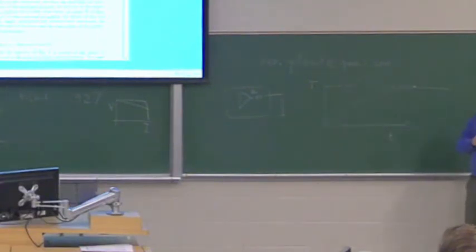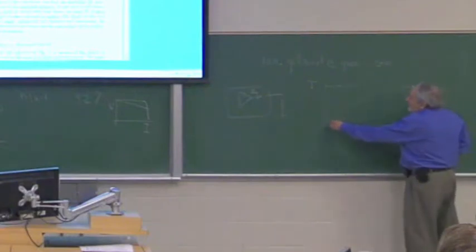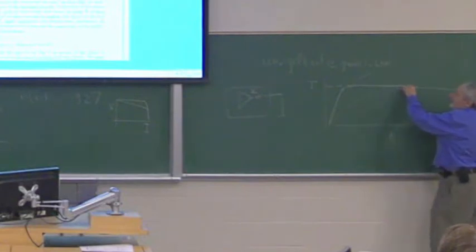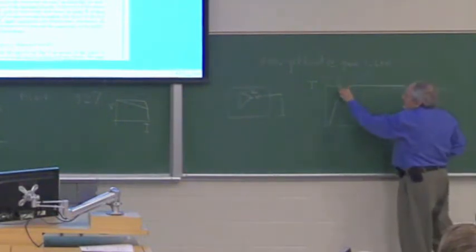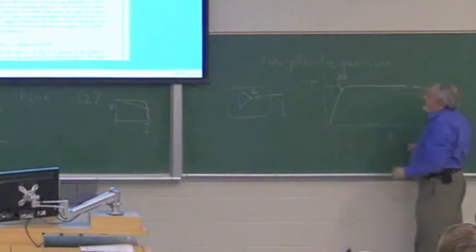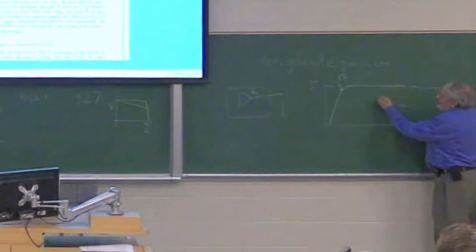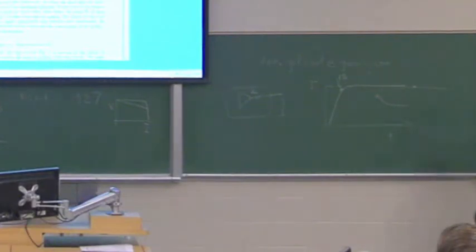But if it has feedback, it can ramp up at very high power until it reaches a temperature and then start cutting down the power. So if it has feedback, it can stabilize very fast and not overshoot. And if it doesn't have feedback, it will take a long time to stabilize, otherwise it will get too hot. This is no feedback. So basically the feedback for a slow plant makes it behave much faster. Is that completely clear? Good.